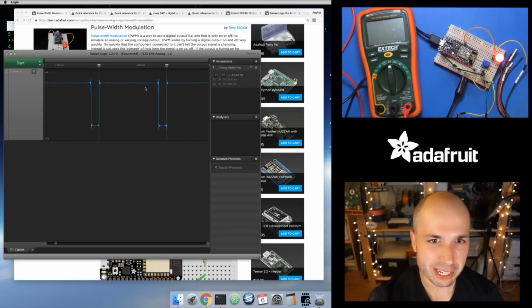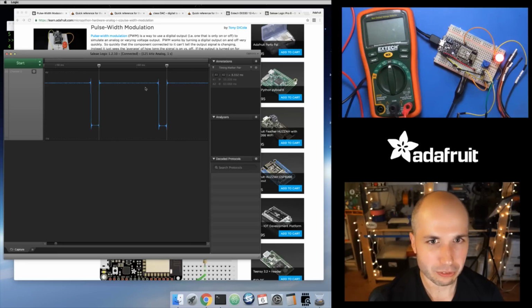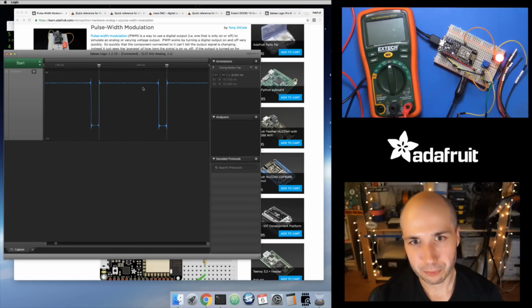Usually you send a sine wave, a nice smoothly changing value, into it, and that's why usually you want to use an explicit digital to analog converter that lets you get nicer control over those voltages. But you probably could, in theory, put a low pass filter after a PWM output, and then throw that into an amplifier and a speaker and get sound out of it. So lots of cool things. But if you just want to make a buzz sound, you could feed a PWM output into a buzzer, like a piezo buzzer, and that'll probably give you what you want. And if you change that frequency, you can change the frequency that you hear with your ears.